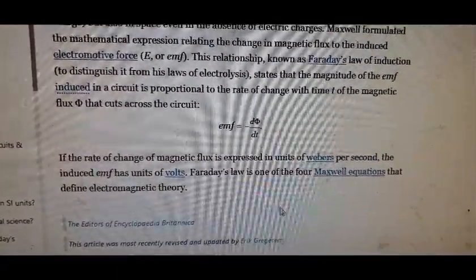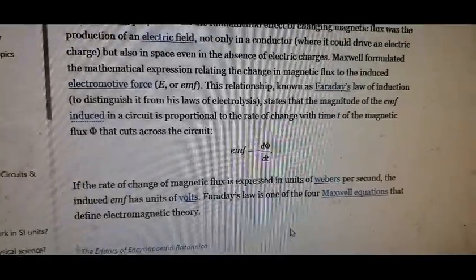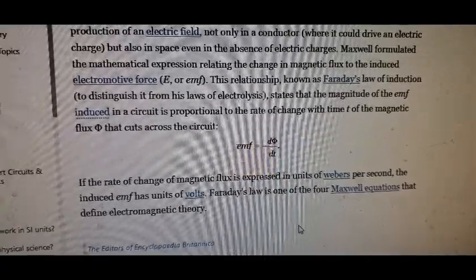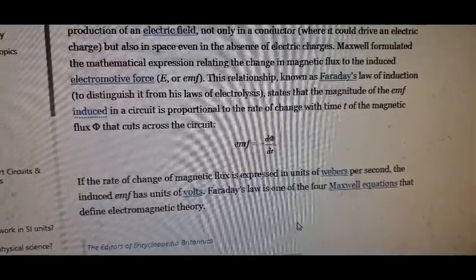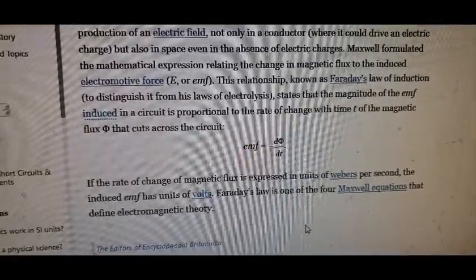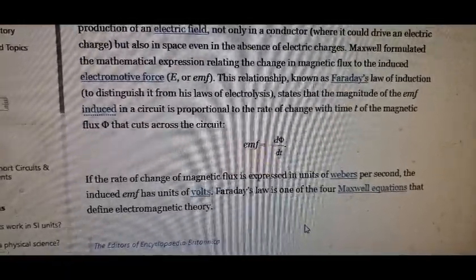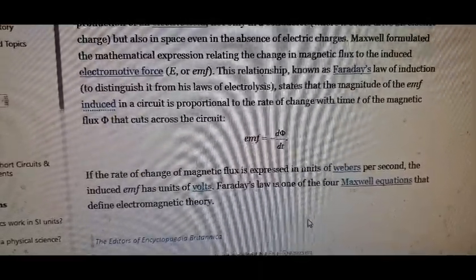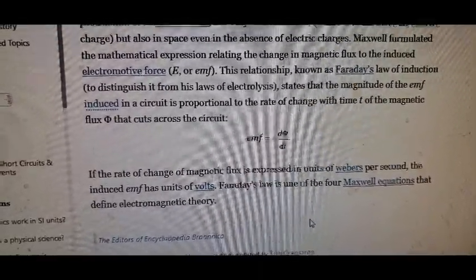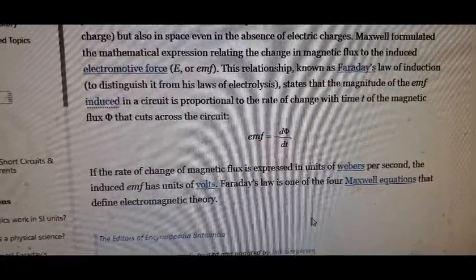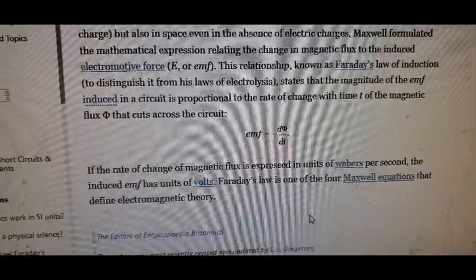If you have an electromagnet with 100 turns on it with a gauge of wire such that when you put in 10 volts, 1 amp flows through those 100 turns, then you have a magnetic field strength of 100 ampere turns, because you had 1 amp going through 100 turns on your coil.